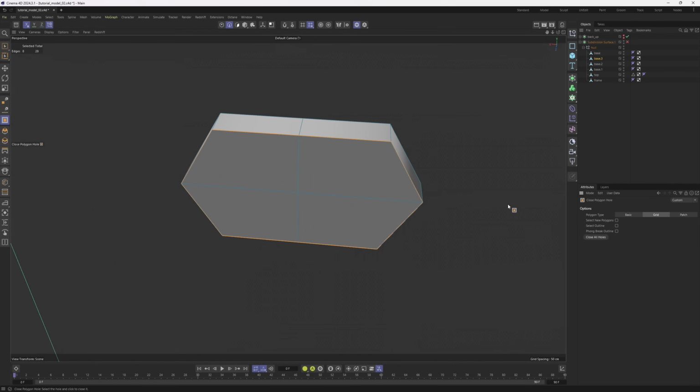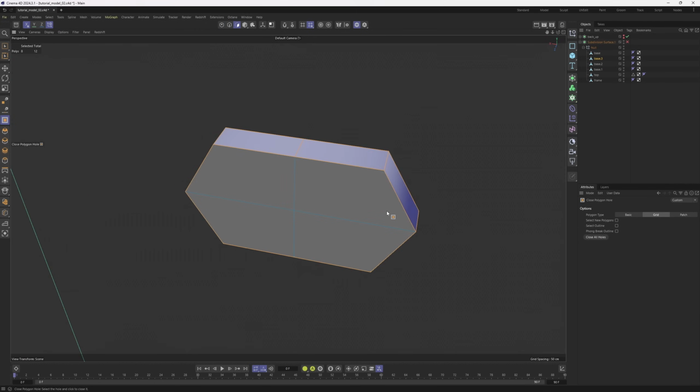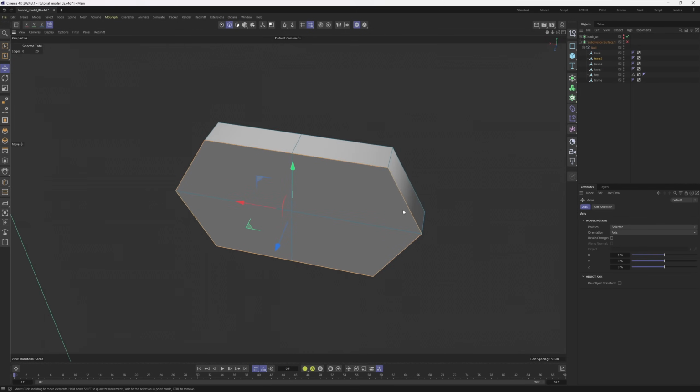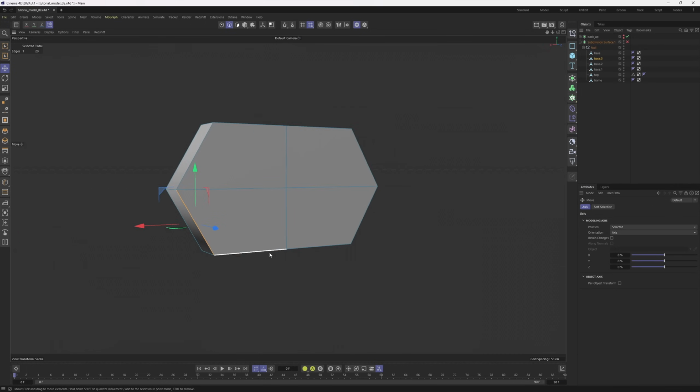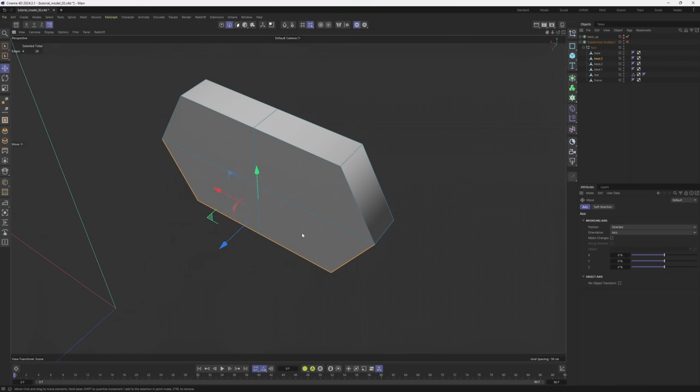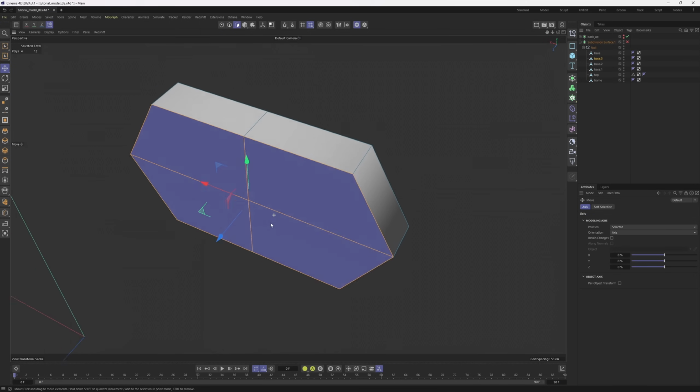I will select the grid one. Grid one usually works the best whenever we have exact amount of points or edges on each side, like we have 4 here and 4 over here. So in such cases, close polygon hole tool with the grid option works the best.